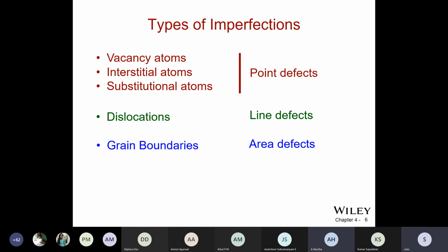But if I cool the metal sufficiently below the freezing point, that localized region where a few atoms took the orientation of the corresponding solid becomes stable. That is called a nucleus. With continued cooling, atoms from the liquid get attached to that tiny solid nucleus, and they keep on growing. This is how the solid nuclei grow into grains. Yes, sir, got it. Thanks.